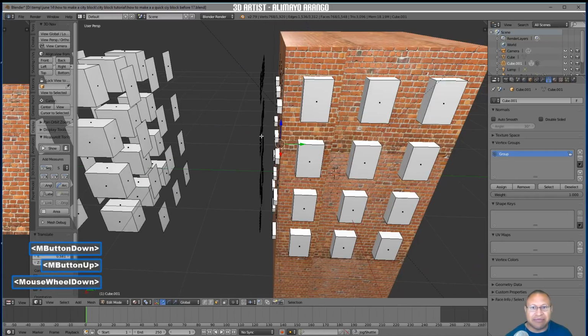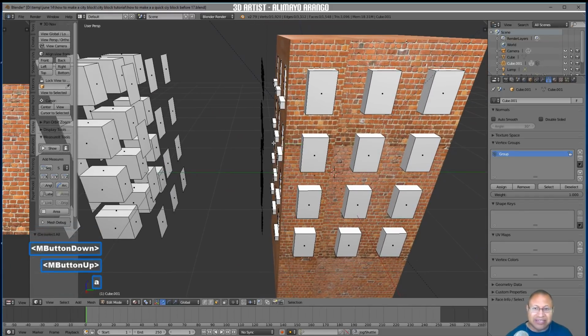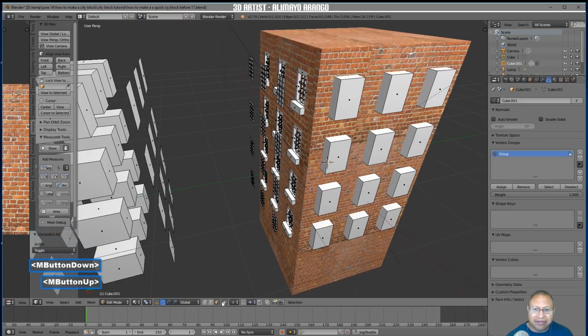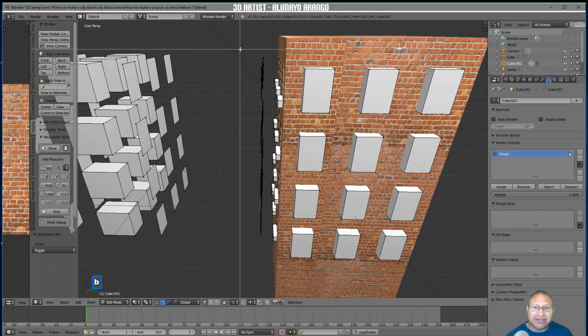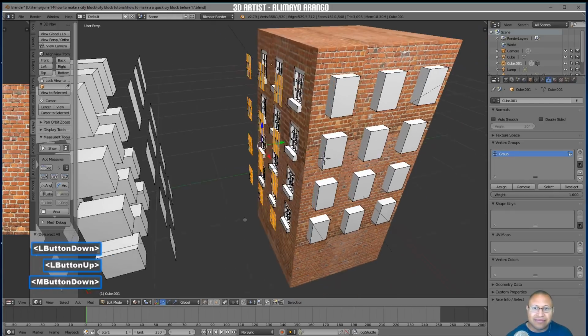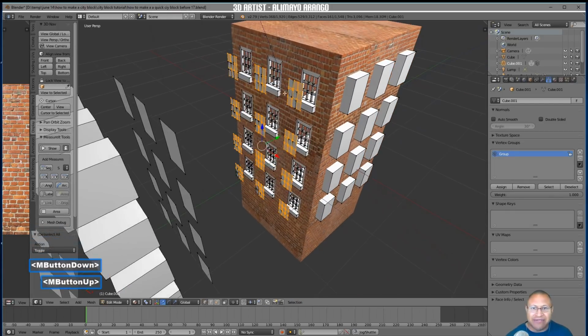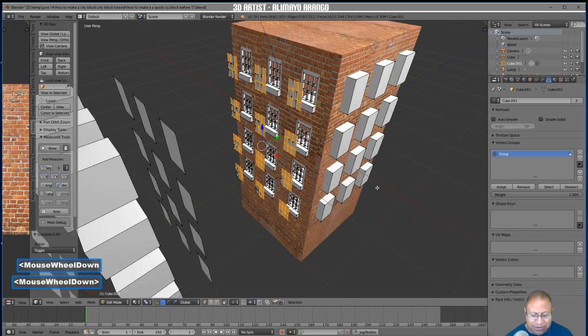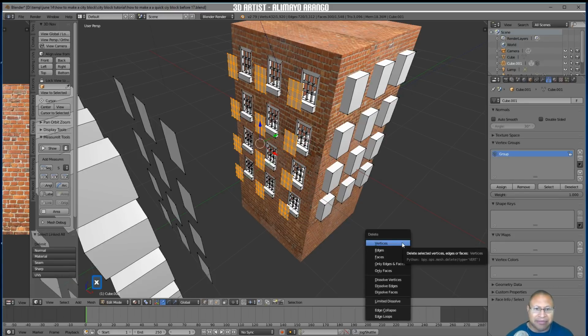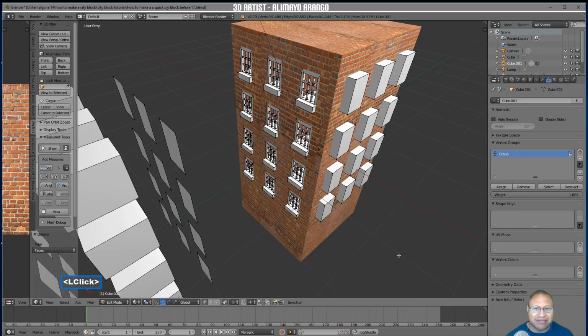And then for this, I'm just going to a side view here. I'm going to press A to deselect. I'm going to press B for box select, and I'm dragging a box. Oh, I'll go to vertex select. I drag a box right here around this unwanted geometry. I have some selected here, but not there, right? Roll the mouse wheel to zoom back. Now I can press Control L to select all of this. Then I can press X to bring up our delete menu and then choose faces to delete.